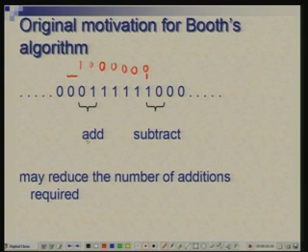All right. So, when this algorithm was devised by Booth, the attempt was made to minimize the number of additions and subtractions which are required. And that was in a context where a step involving addition will take longer and a step not involving addition will take shorter time. So, the attempt was to see if there is a string of ones, instead of doing 1, 2, 3, 4, 5, 6 additions, you perform 1 addition and 1 subtraction. So, there is a speed up there.